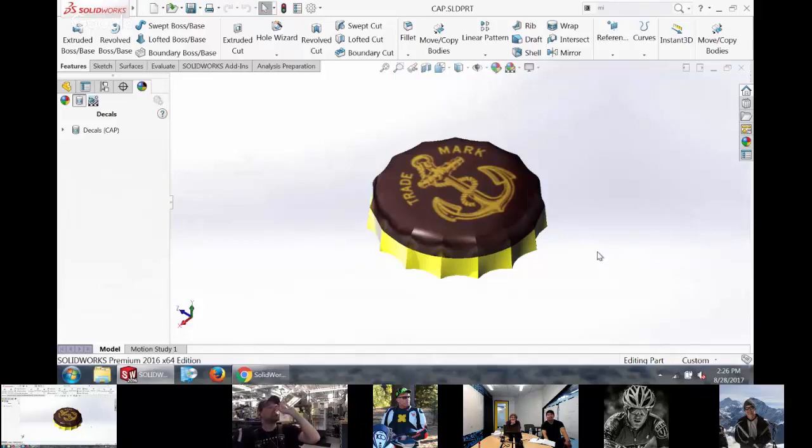What I want to talk about is file references. So we were talking about external references before. That has to do with geometry, one file looking at the other. The file references, when you go to open an assembly, you know, there's that list of files that you need. And if you can't find any of them, it'll say, I can't find this. Would you like to find it yourself, etc. There's something called a recursive search, and it's how SolidWorks looks for a file. It does not actually always go to the folder that you think it's going to go to. If you have a part open in RAM, that's good enough. It'll stop looking. So I've got this part called cap.